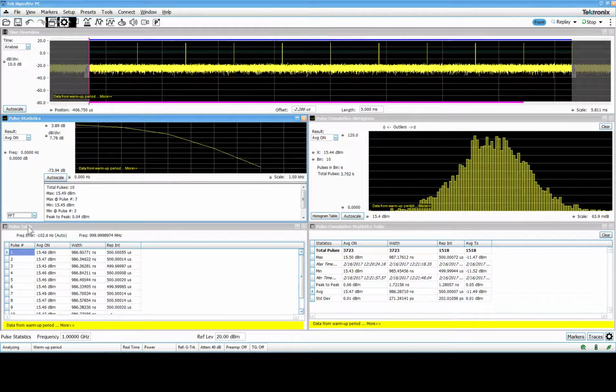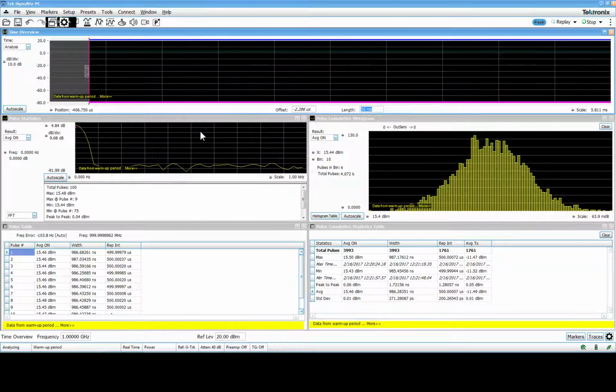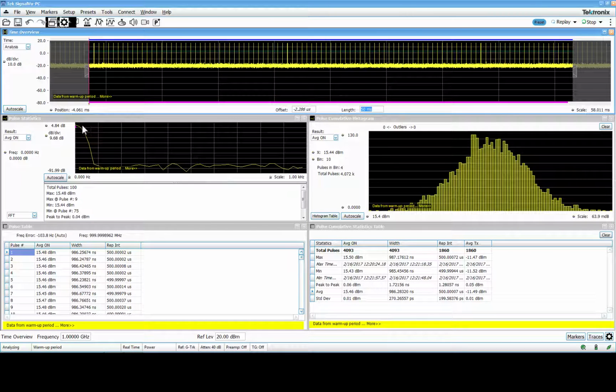And the FFT is very good if you're looking for leakage or something, because if the average power is kind of modulated, we probably need more pulses. Let's go to 50 milliseconds. You can actually do an FFT of the results, and you can see there's a peak here. But normally what I've seen is peaks over here, and that's actually from some power transmission or DC-DC converters.